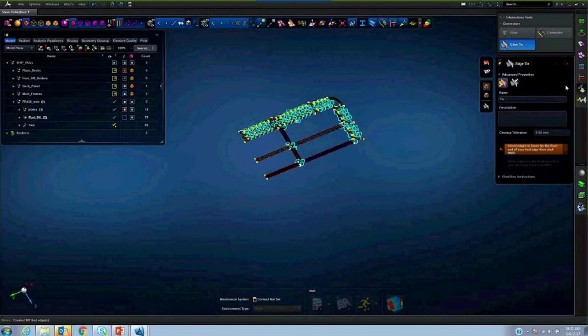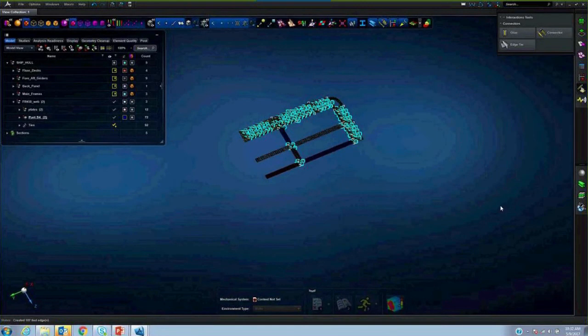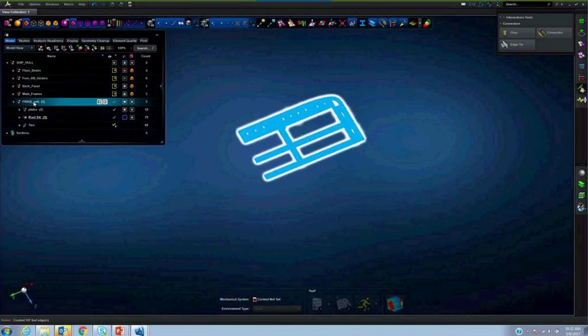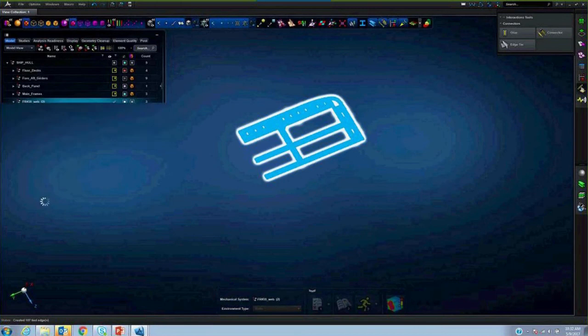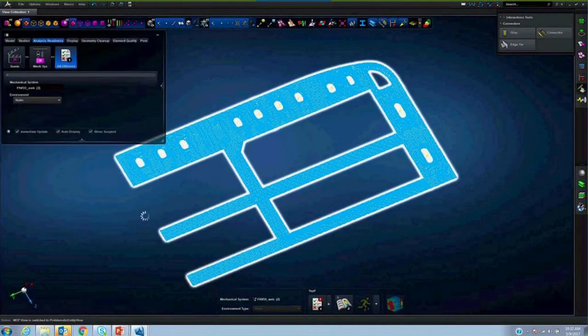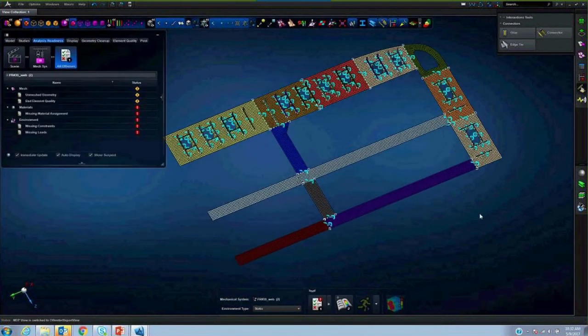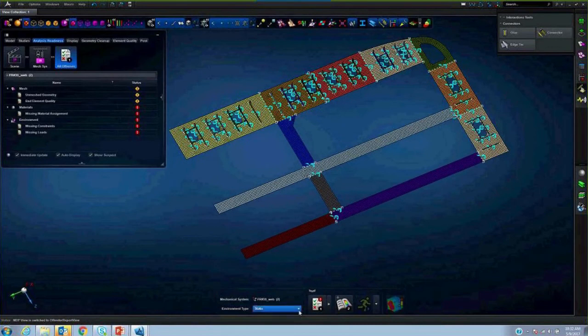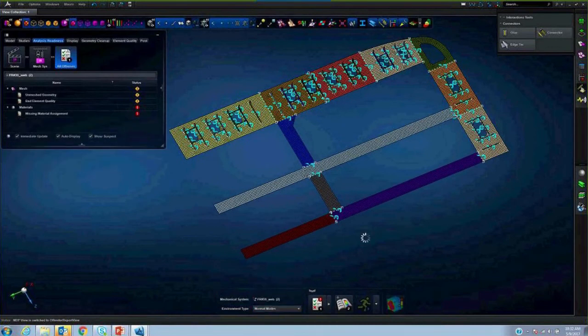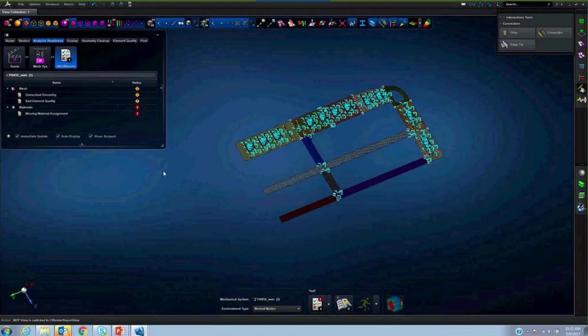And now, is this ready to run? And is this a validated model so that we can assemble with the rest of the parts? Let's set the context of that subassembly to validate this model, and we can run this one to validate by conducting the normal modes analysis. And as we set this to run normal modes analysis, it's saying that it is missing material.